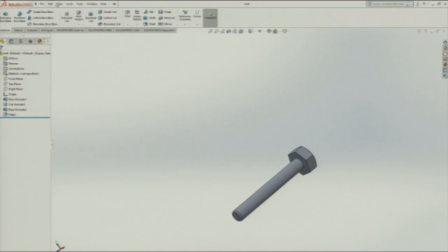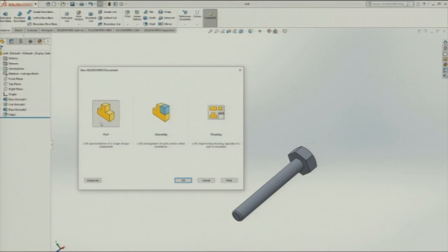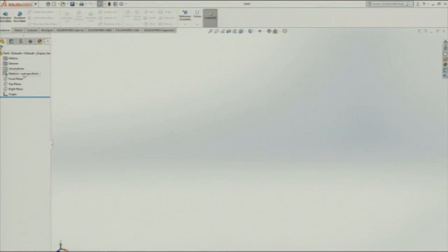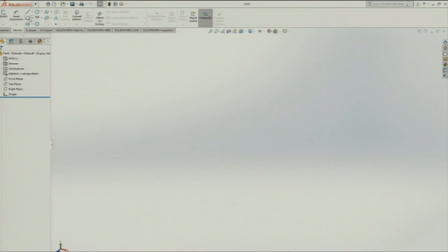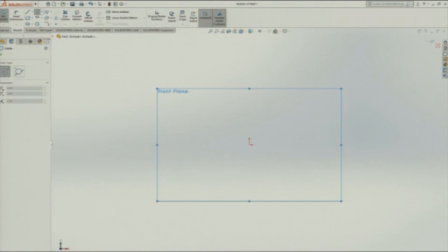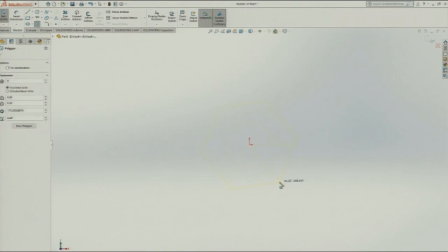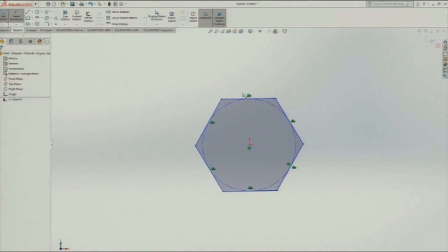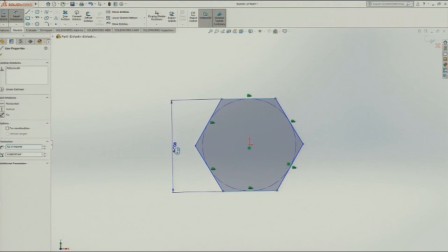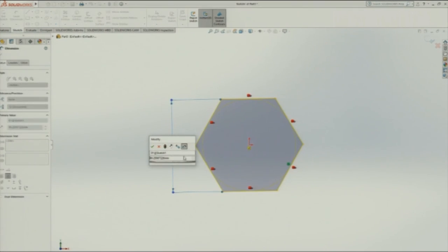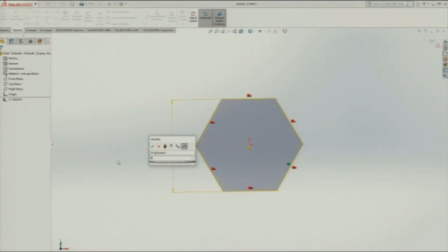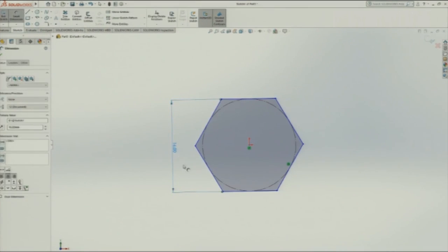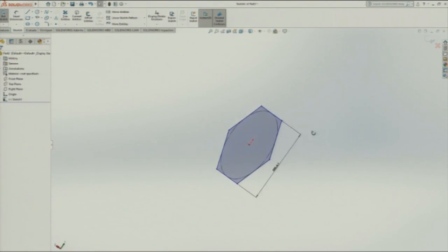So, similarly, I will select a new part. The new part I am going to make is a nut. So, sketch: first I select the plane, normal to the plane, then circle, okay, hexagon first. So, again, same size 60, then this is 2D, this is 16, this is 16, twice the dimension, the customized bolt selected. Okay, applied.